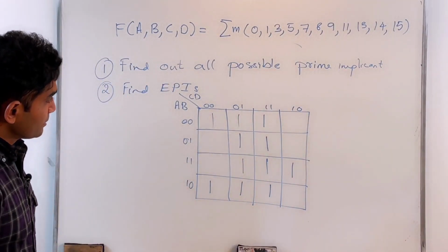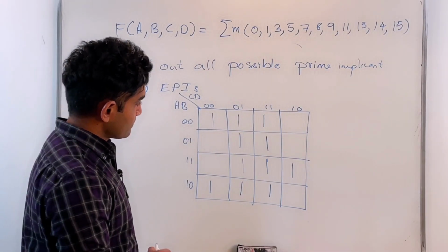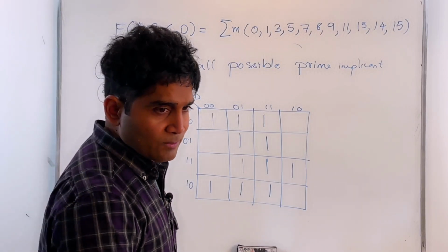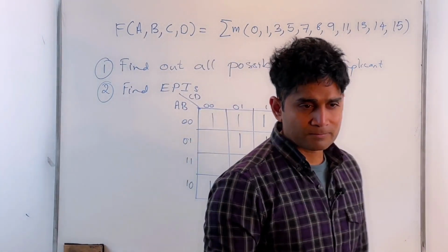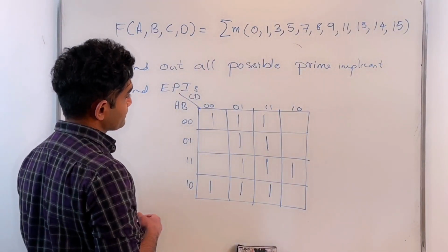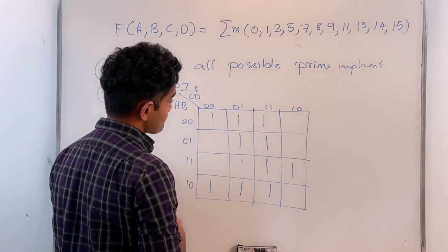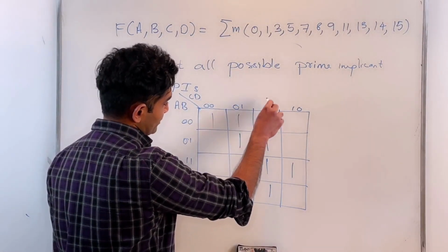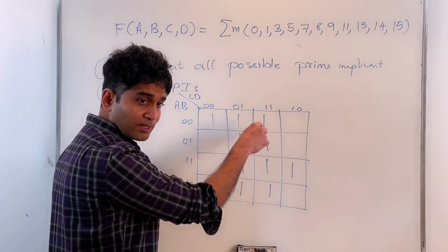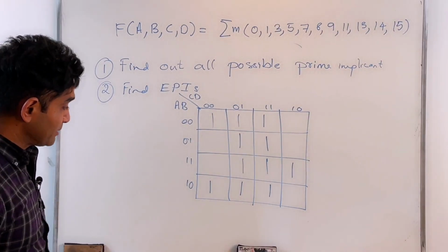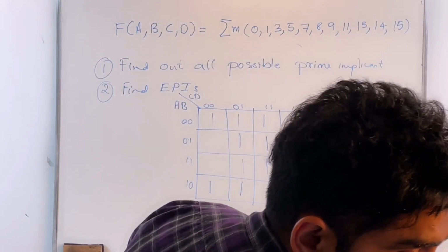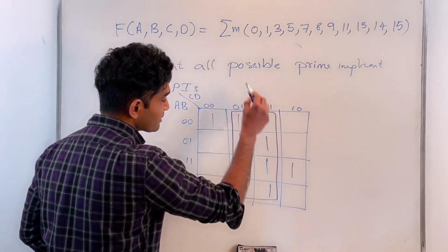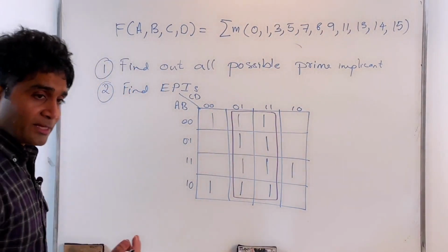Okay. So what are my prime implicants now? Do you see any prime implicants? D. Okay. How do I get that? In all cases where D is 1, they're the ones in its place. Okay. So I can see you have a combination of 8 adjacent cells. That's a power of 2. I can combine them into a single combination. So let me do that. I can already see that. That's a combination of 8 adjacent cells, 2 power 3 is 8.